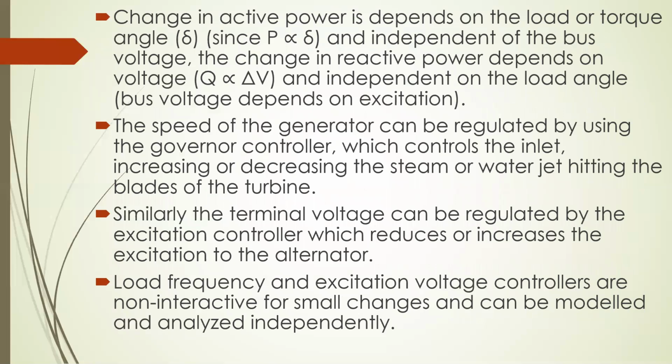Here is the same point which I already discussed: change in active power depends mainly on the load or torque angle. Previously I told that load, now the torque angle also matters. That means active power mainly depends on load as well as torque angle.